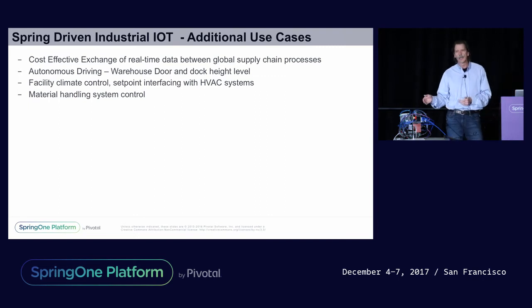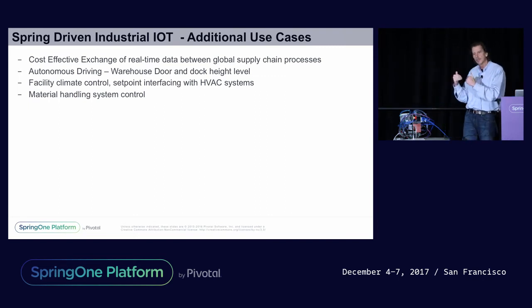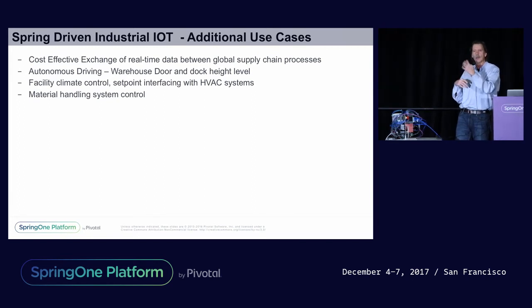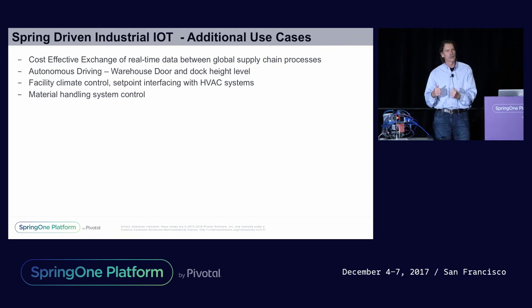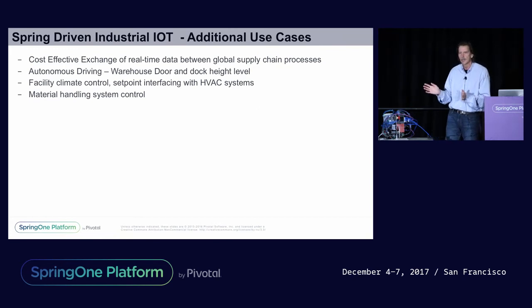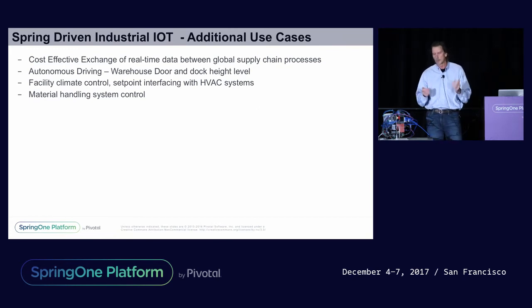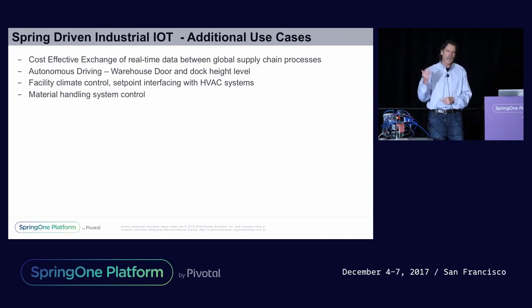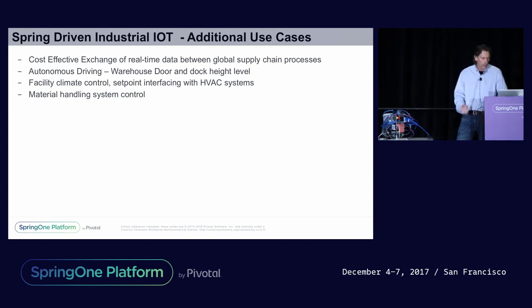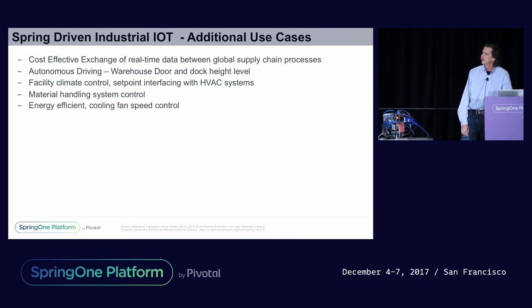Then using a gateway like this, you could pass that information, which typically you would have the person and their barcode up in the enterprise, down to the low-level controllers that are controlling the conveyors and the diverters to send it to a specific location. Using the gateway, we can pass that information from the enterprise to the lower-level control system.